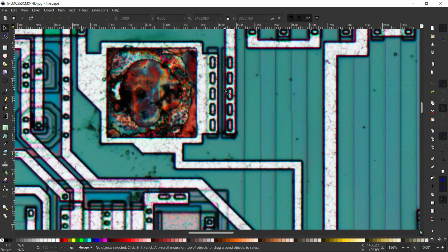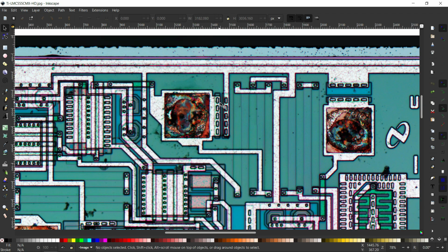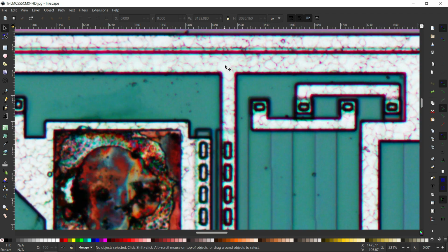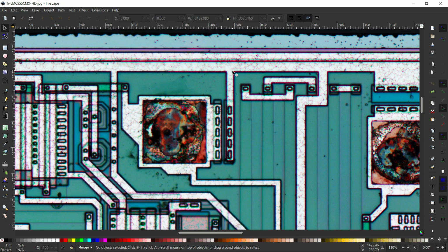So next to the pad, wherever the pad is there, they have some device. It looks like a source and drain kind of structure, but this is not a source and drain structure. By using the MOSFET they have implemented a diode here. Maybe the gate terminal and one more terminal will be shorted together and it can act as an ESD diode. Other than this ESD diode, usually they will connect it to the ground pad. We'll discuss where the ground pad is and the routing from the ground pad, the complete routing style, everything later, one by one.